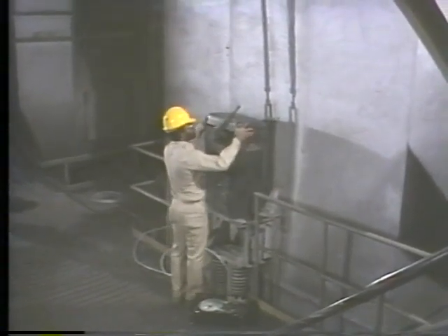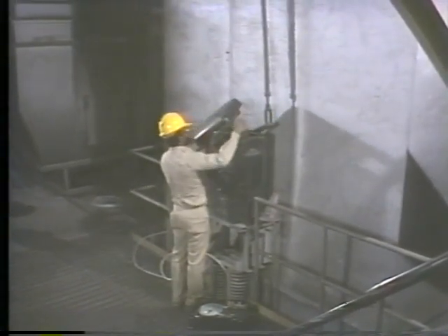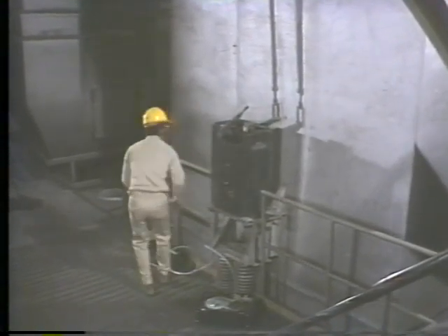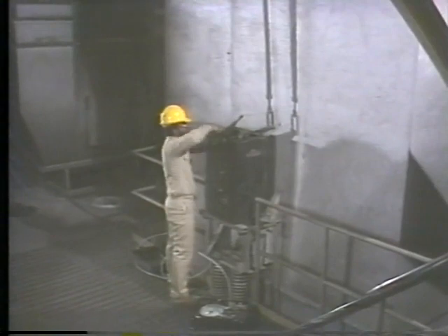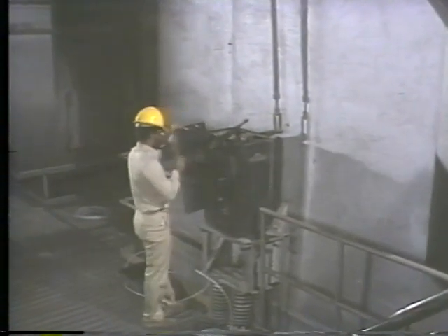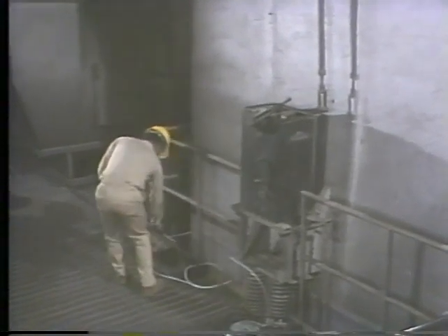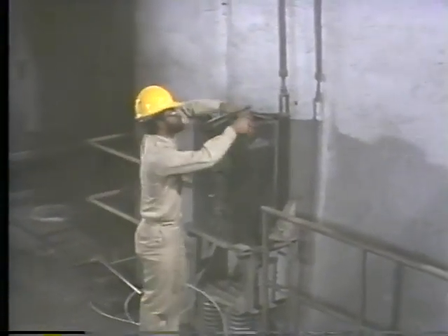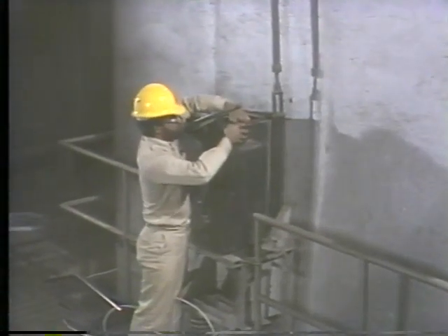Both the piston actuator and the positioner are enclosed in a metal shell, similar to the one we saw back in the shop. Before beginning work on an actuator like this one, it's a good idea to shut off the flow of supply air to the positioner. This locks in any air pressure in the piston cylinder and prevents the piston and actuator linkage from moving unexpectedly.